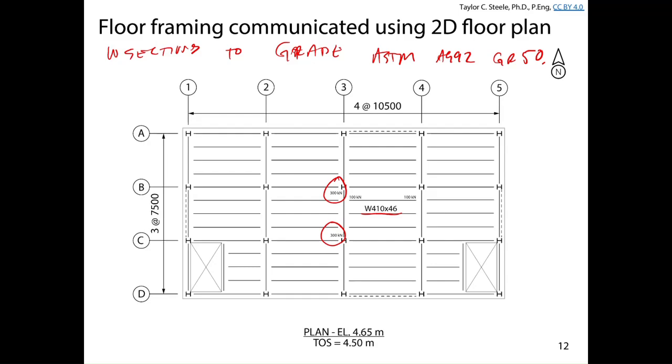So whenever you're using structures, you need to communicate this information to the people who are going to build it. They need to know what to buy. And so if you've got HSS or plate steel or wide flange sections, you basically need to tell them the grades. You need to tell them what bolts you're using, what electrodes you're using. And so there's a lot of additional information that you need to outline on the drawings. Think, if somebody needs the information to build it, it should go on the drawings on the representative framing plan.